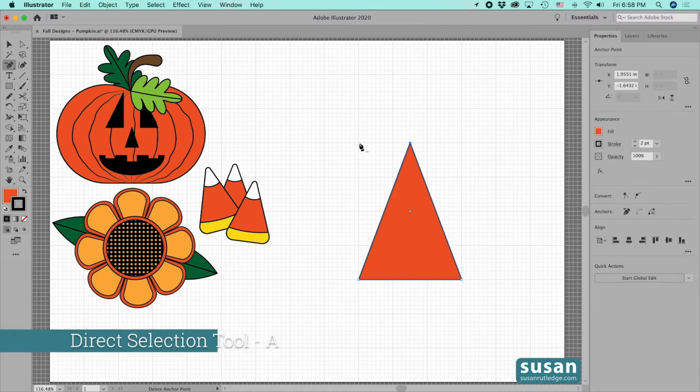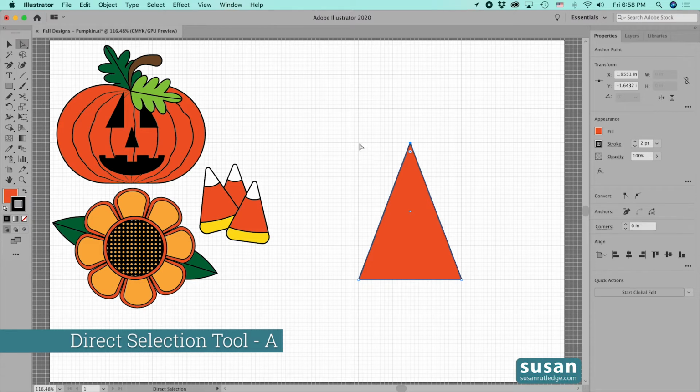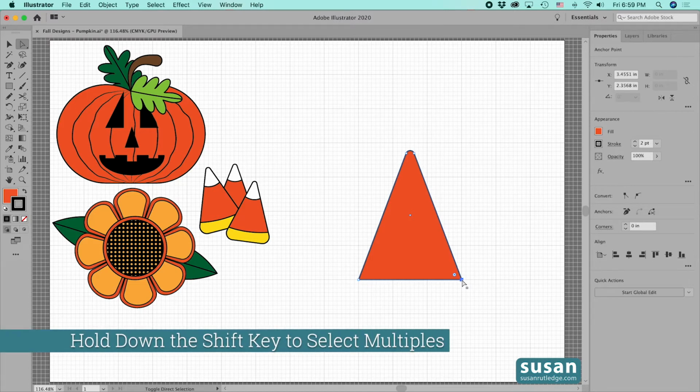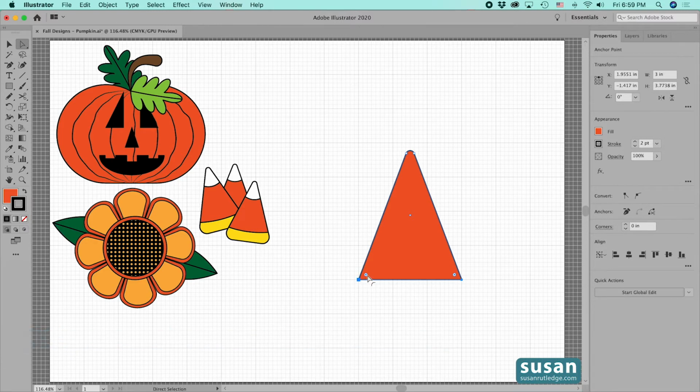And then I'll get the Direct Selection tool, keyboard shortcut A, and that's found on the left toolbar as well. I'm going to drag just ever so slightly on this little handle down to about 0.12 of an inch and release my mouse, and then click on the artboard to deselect that anchor. Now I'm going to select the bottom right anchor and then hold my shift key down so I can select the bottom left anchor at the same time. And I'll drag these anchors up to the center and probably, let's stop here, 0.32 of an inch and release my mouse.